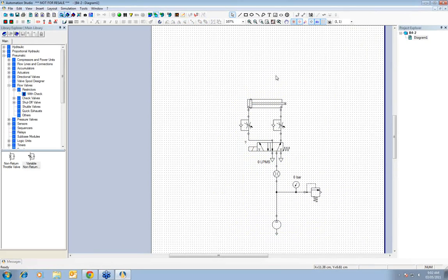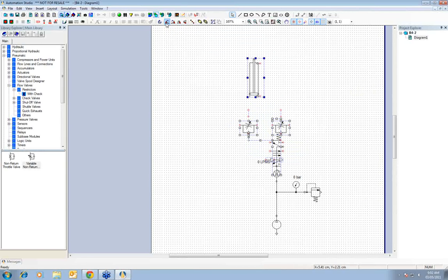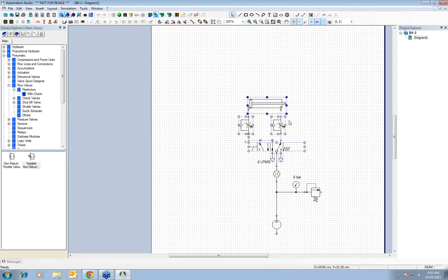Once it's done, the exercise that I'm about to do is I want to make sure that all of these components will be pointing into the left. So if I select all of these components and then suddenly choose to make a left rotation, as you can see, it flips all the components individually, which is not what I want. So I'm just going to do Control Z. If you want to flip all the components all at once, you have to group those components first.